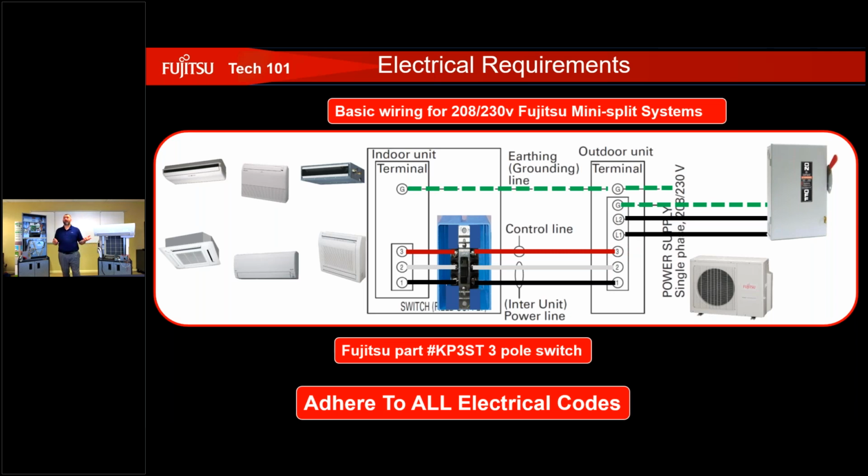So now where do we send our DC reverse serial signal, if we have power on terminal 2? Because remember, that's where the reverse signal was sent with that 112 volt system. That's why we have that second ground at the outdoor unit. That second ground makes the outdoor unit and indoor unit be able to differentiate the DC voltage and AC voltage, which is traveling through terminal number 2. Okay, so we have actually both of them present there.